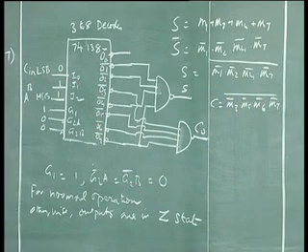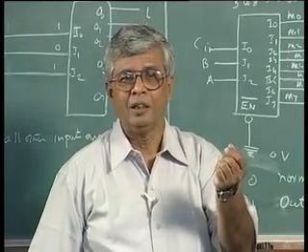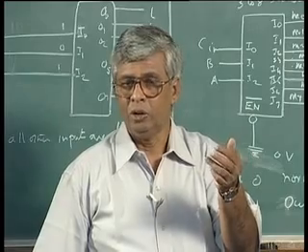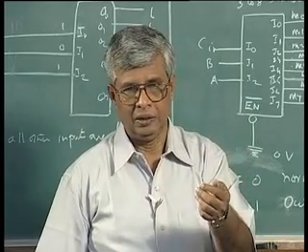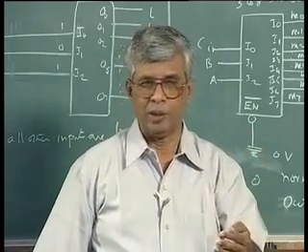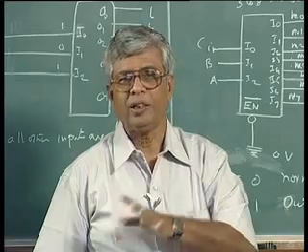So some of these practical things you should know. That's why I thought I will introduce this. When you look at a circuit, logically you may be right, conceptually you may be right, but then it will not work because you are assuming the outputs will be active high, but they are really active low. Or you did not know there was an enable which has not been properly connected. Or you did not give the proper power supply voltage and ground. You should know which pin has to be given power supply, which pin has to be given ground. So all these things you should know.